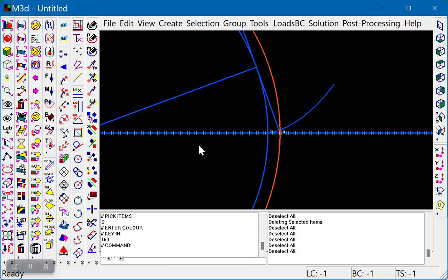So I can use the offset command here. If I select the offset command and type in the offset distance, which is going to be for the dedendum 1.5 times 1.25, and then if I select the pitch circle and then click to the side I want to offset it, that's giving us the dedendum circle. Right click and cancel out of that command.